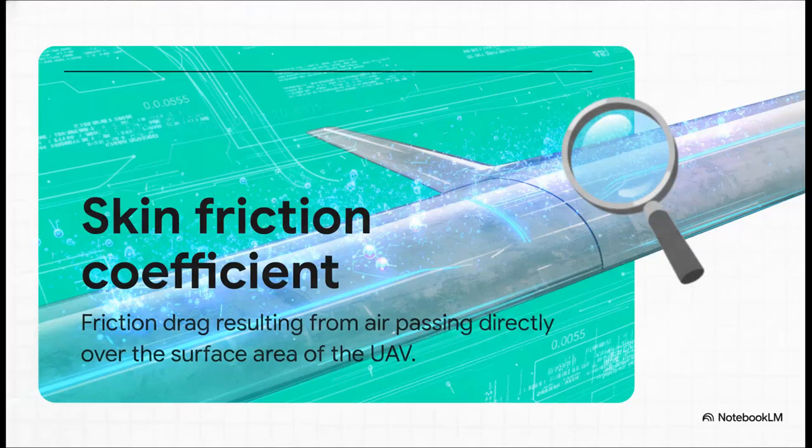Drilling down even further, we get to the skin friction coefficient. This tiny decimal, 0.0055, represents the physical struggle of the air literally grabbing onto and passing over the vehicle's surface. It's so low because they specifically utilized ultra-smooth composite materials for the outer shell. It's a highly deliberate choice, so the air molecules just slip right past with minimal microscopic resistance.